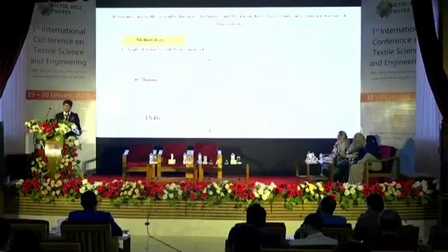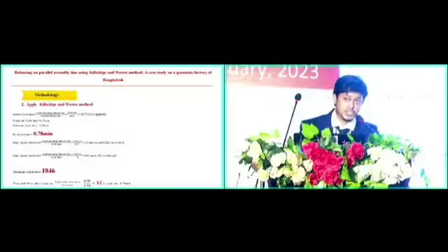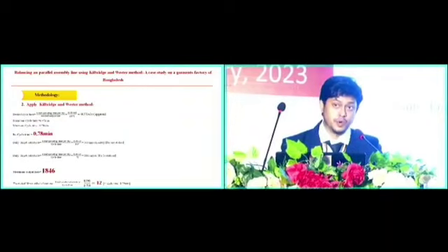I have to calculate the total operating time per day, which is 3 into 8 into 60. I have 3 shifts in a day, 8 hours in a shift, and 60 minutes, and divided by desired output rate, which is 870, which I found from the factory's OBS report, which leads to 0.77 minute.